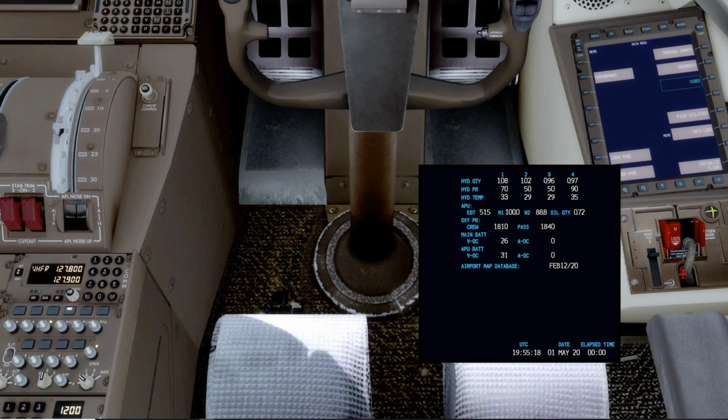Now at the same time, if you're going to do an oxygen check, which we can't really do because I don't have two mice to do this, you'd have to come over here and go to the RT position. You're in flight, you're in speaker, and then when you go to RT, you'll hear the sound of oxygen across the oxygen mask microphone and through the speaker.